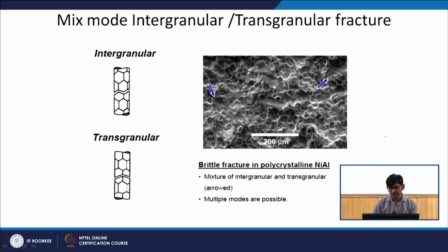They are already quite easy to separate at high temperature. So, the crack propagates through the grain boundary when you have high temperature fracture, in some cases, not always. So, in high temperature fracture also you will see this kind of fracture feature. Sometimes it can be mixed mode also, you can get intergranular, you can get transgranular. So, you can see these are all with faceted features, you can see a faceted feature here also.